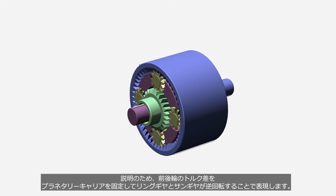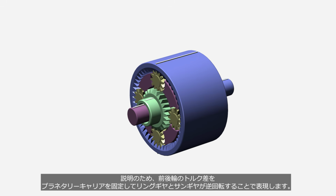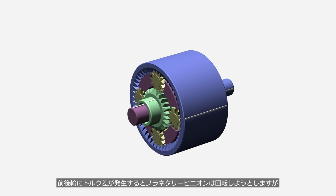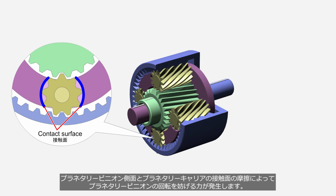To illustrate the torque difference between the front and rear axles, the planetary carrier is fixed, and the ring gear and the sun gear are rotated in opposite directions. When a torque difference arises between the front and rear wheels, the planetary pinions tend to rotate, but friction at the contact interface between the planetary pinion sides and the planetary carrier produces a force that opposes this rotation.